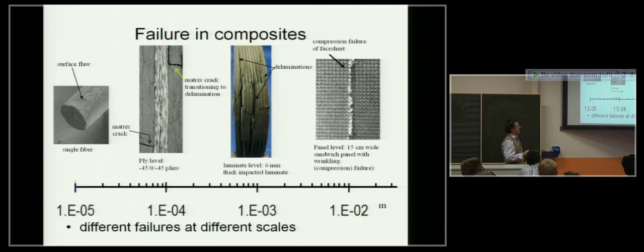Here we have 3 different layers. This one to the left of the white region or the white-gray region, this one is a minus 45 ply. We'll talk about directions and orientations much more later on. The one in the middle is 0. So essentially the fibers in the middle are running along the length of the photograph shown there. That's why it has completely different color. And then we have again minus 45 on the other side. Basically the little dots that you see are the actual fibers coming at us.